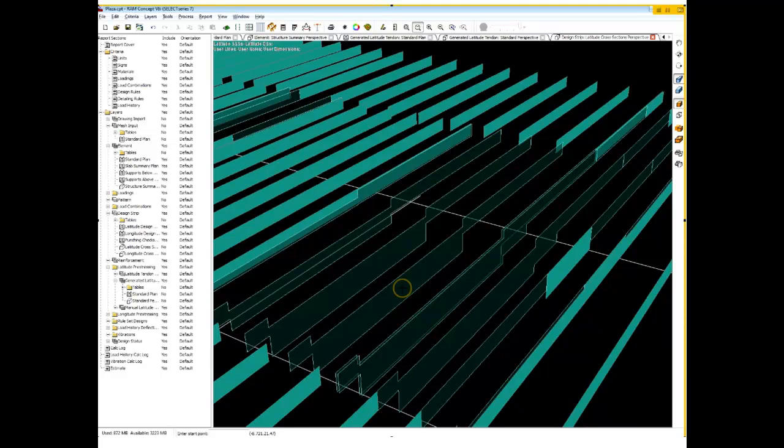Because of this cross-slope limit, it can cause an error where virtually there's no concrete within the cross-section. And we're kind of seeing this phenomenon here, where it's not that solid color, so what's going on? There's no information. If there's no concrete in that situation, of course you're going to get an error, and you're not going to get any detailing in that location.